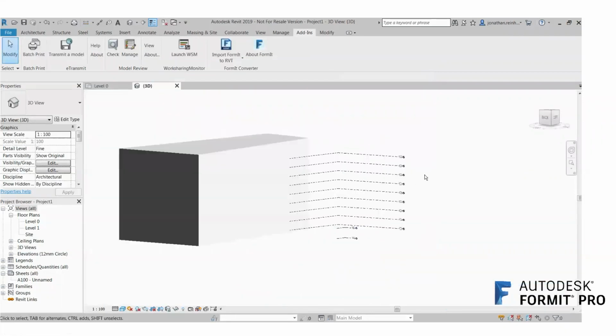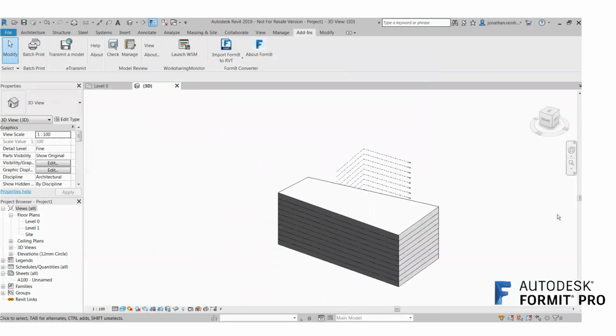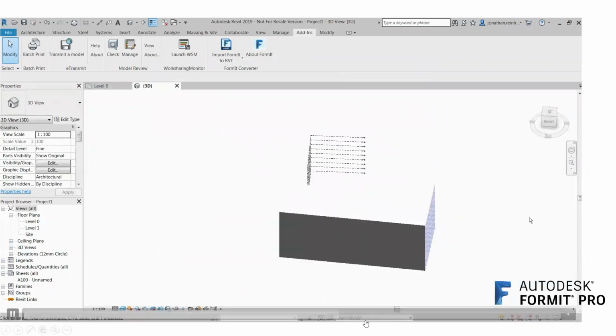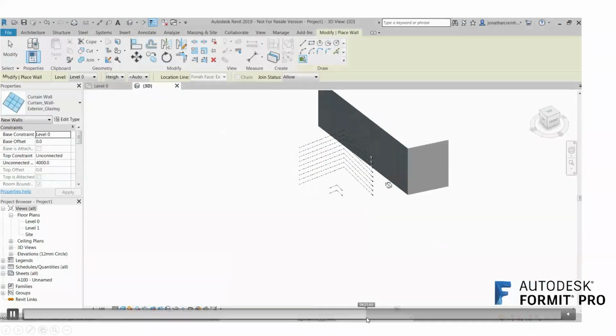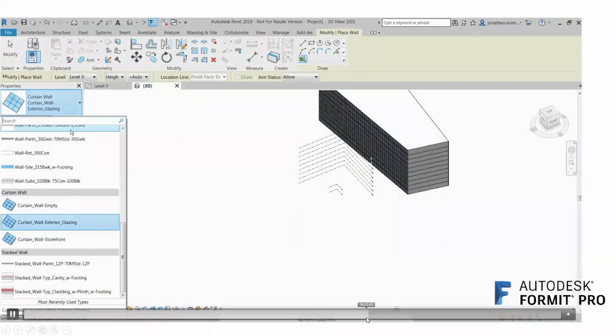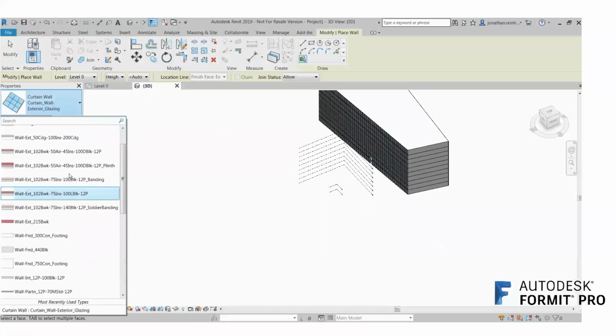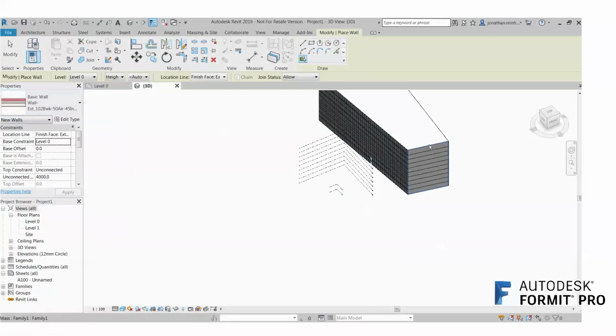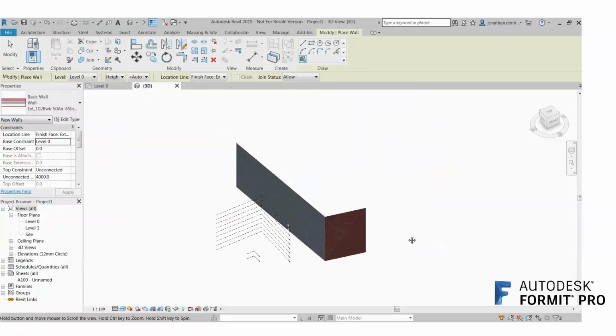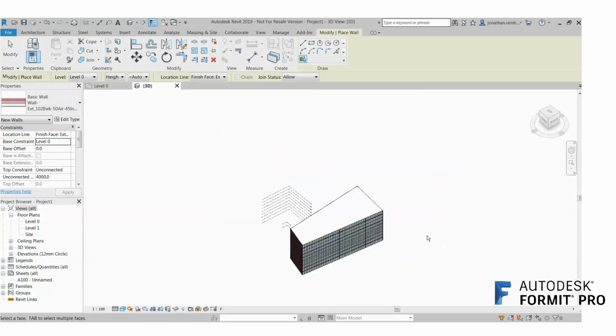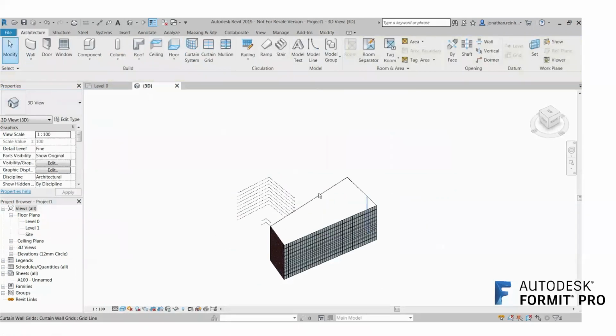Just going to turn on my mask there, and you can see that I've created that mask there as well, just brought that in. So now I'm going to convert that into walls and windows. So I've used my curtain wall tool just to convert that into curtain walling, and you'd see you just click create wall by face just by using the tools directly within Revit.